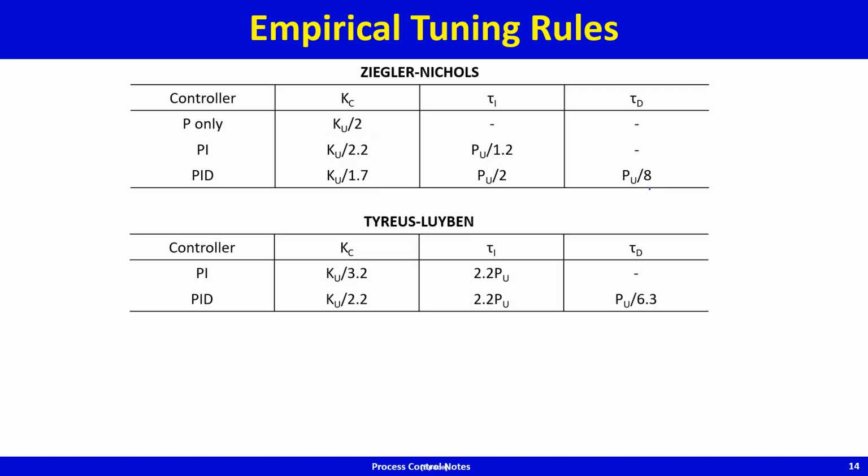On the other hand, the Tyreus-Luyben tuning rule, you can see it is much less, or significantly detuned from the Ziegler-Nichols gain, with significantly higher reset time, and so these very conservative tunings actually ensure gentle manipulation. So you get there eventually, slowly but surely.